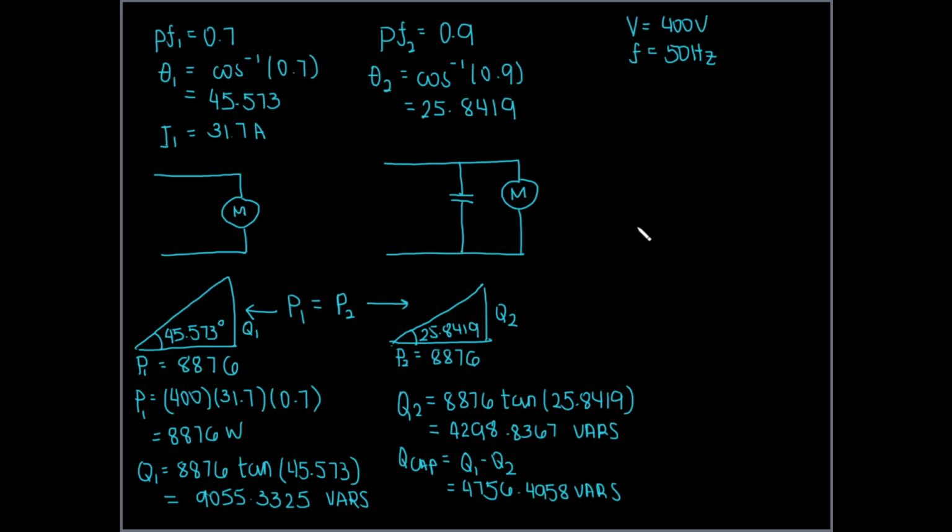However, that is not the final answer we are looking for, but it will help us solve for the final answer because we know that that Q is, it's single phase, right? I will change the color of my pen because I can. That Q is, remember, it's the voltage. There's no such thing as line to line or line to neutral anymore because it's single phase, divided by XC.